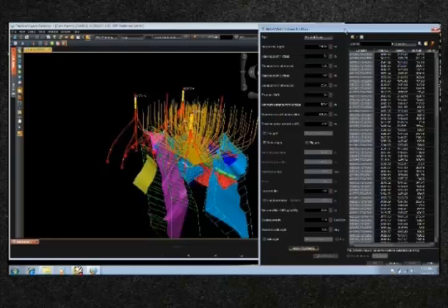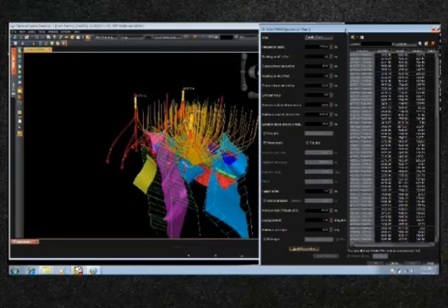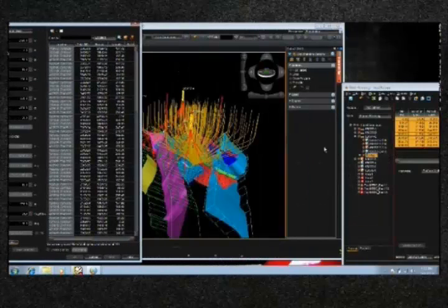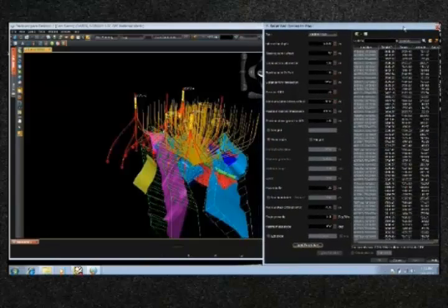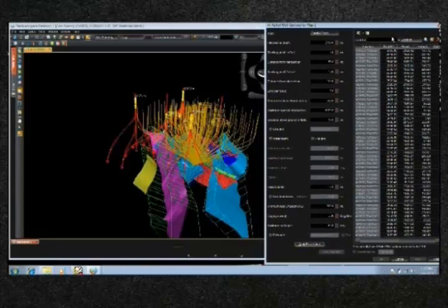There are some important criteria to consider when it comes to the surface locations of these relief wells. These are dictated by various factors, primarily a safe distance around the target well, but as well as other parameters such as the behavior of the plume, as well as if there are any existing obstacles on the seabed, in this case. What we have done in this demonstration is we have outlined three areas from which to drill our relief well plans from. These are indicated in the yellow circular zones in the 3D view.